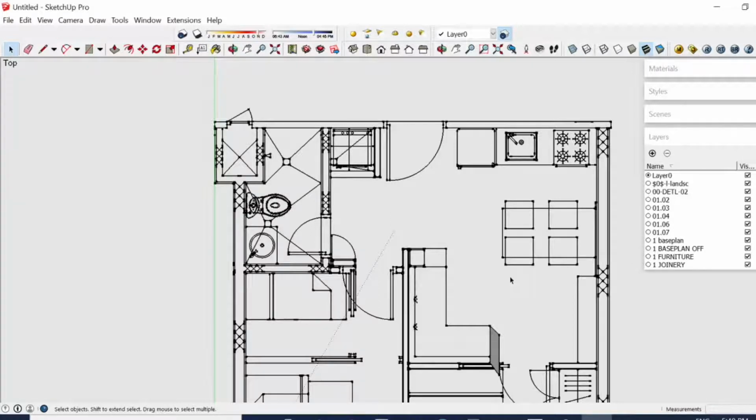If deleting those vertical lines won't affect your floor plan, it should be fine since AutoCAD snaps on the endpoints. Unlike the image file that some designers opted to use, it doesn't have snaps.